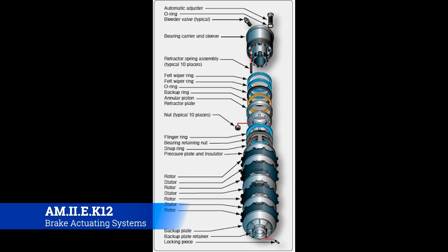Okay, so runway length and speed are only two components that might lead you to need more aggressive brakes. The other thing that you might need to take into consideration is the weight of the aircraft. Now, a multiple disc brake system is very common in older airplanes, and the reason is that the older transport category aircraft generally are very, very heavy.